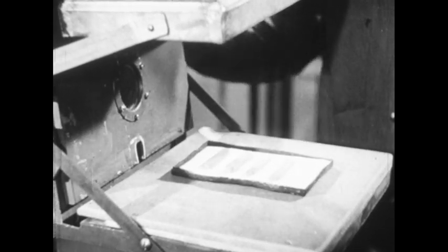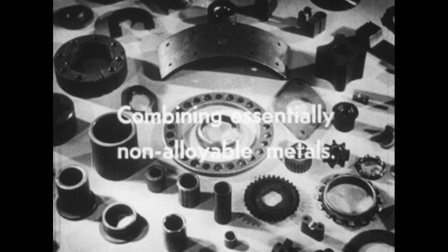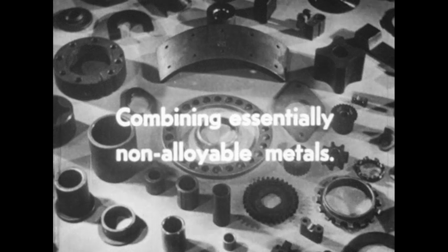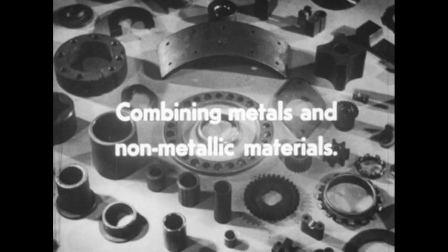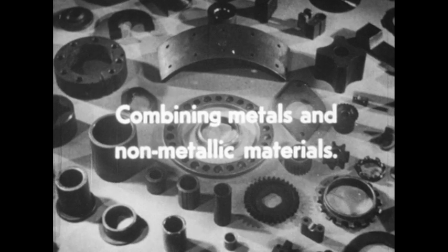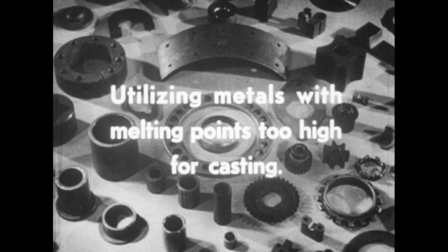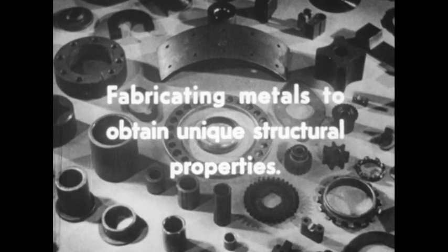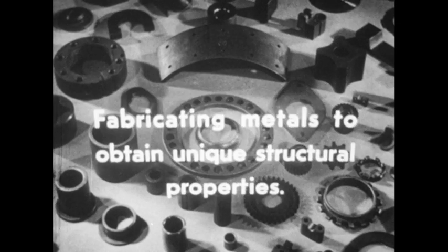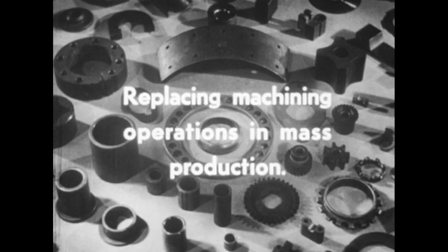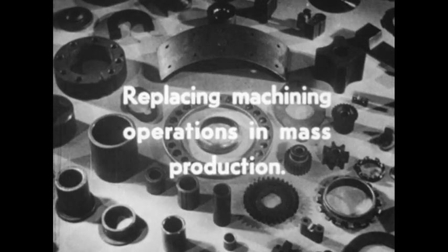Powder metallurgy is thus employed to make a wide variety of industrial products. It provides the means of combining essentially non-alloyable metals, combining metals and non-metallic materials, utilizing metals with melting points too high for casting, fabricating metals to obtain unique structural properties, and replacing machining operations in mass production to save time and material.